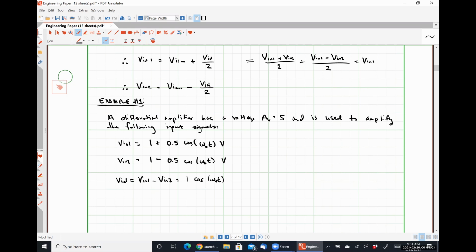So we would say that we have an input voltage swing of twice the amplitude of our original sinusoid, right? Because we are subtracting away some portion and these two signals are completely out of phase with each other, our differential input signal is actually experiencing a boost or an enhancement, right? Because they're both 180 degrees out of phase, the constructive interference between those two is going to make our amplifier see a differential signal that's twice as large as the AC portion of either of our inputs.